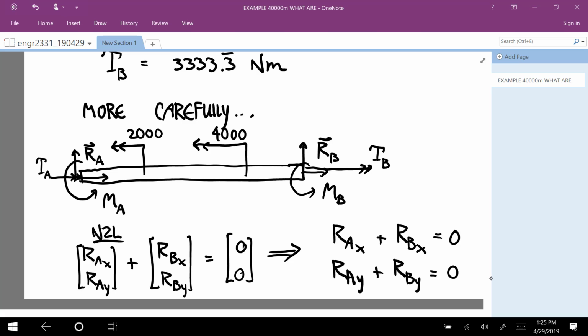If we wanted to calculate that, we'd have to use a statically indeterminate approach, using first elongation, then deflection, which we haven't done yet, and then the torque. And what we would see is that all of those things I left off will end up being equal to 0. But instead, on these problems where there's no vertical forces, no horizontal forces, we'll just leave those out, because that's what it would come out to be anyways.